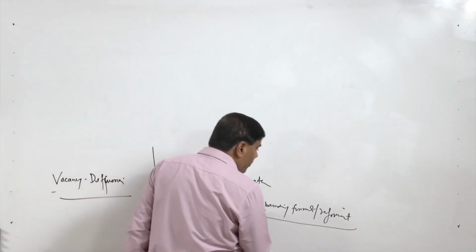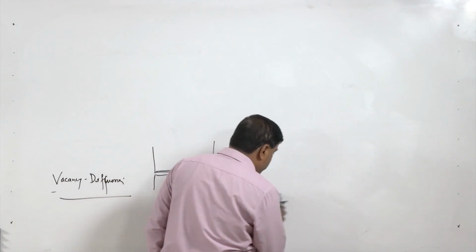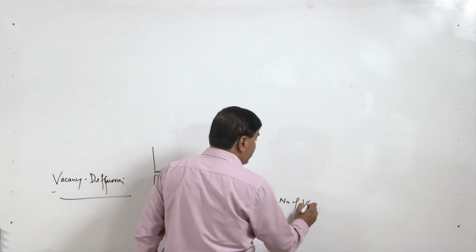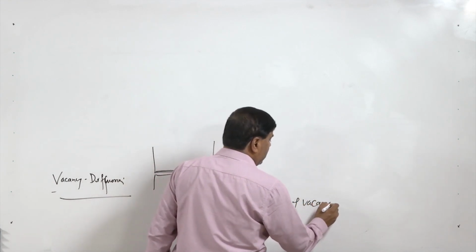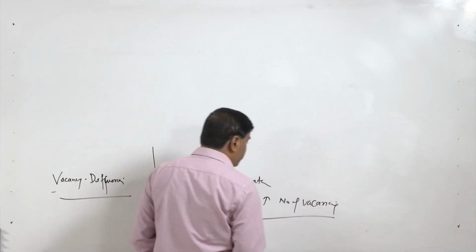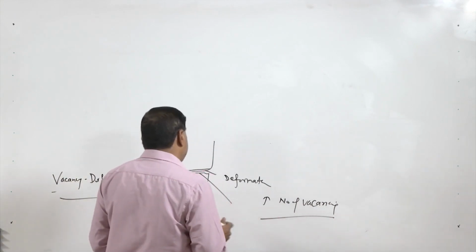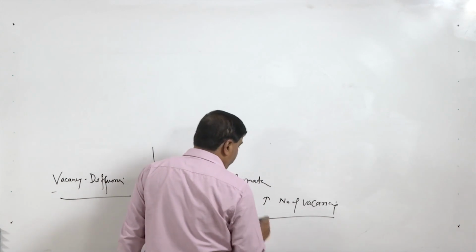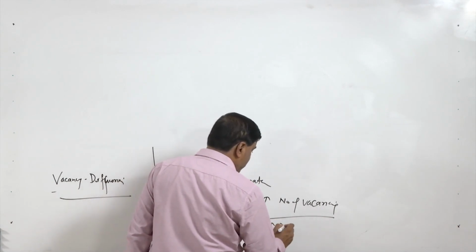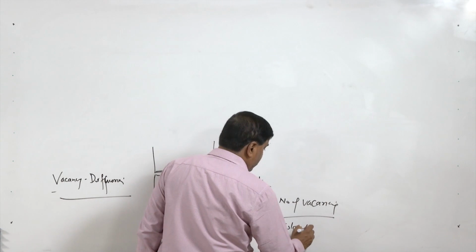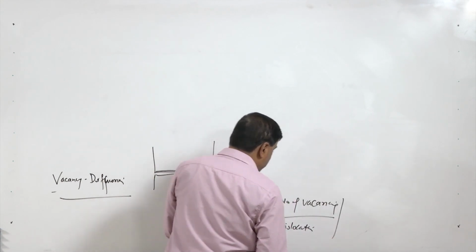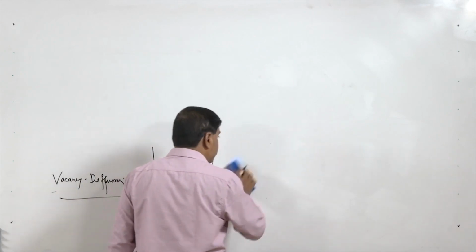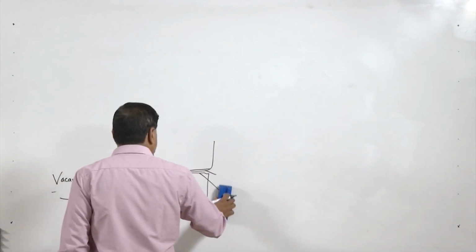So, grain boundary formation through grain refinement, and increasing the number of vacancies through the deformation, will further facilitate the diffusion. The deformation will also increase the dislocation density in the near surface layers. These will further provide opportunities for the atoms to diffuse.